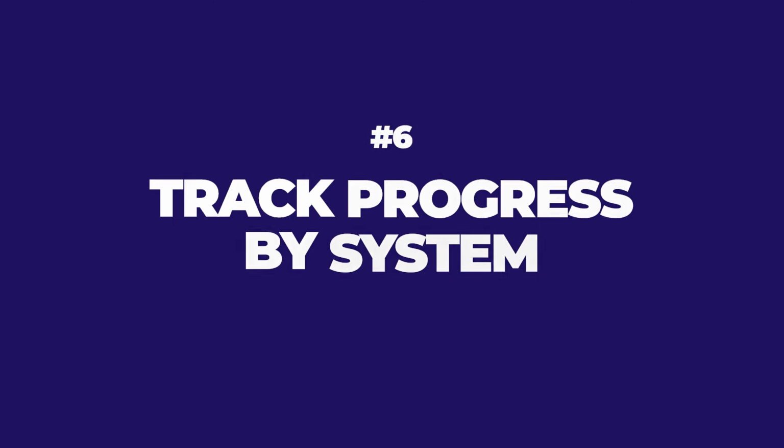Number six, like I said, track progress by the system, not by location. I wouldn't do it floor by floor. I literally would get out those flow diagrams and those one-line diagrams, and that's what I did on the first project where I was doing this, to schedule dates for different segments and pieces of equipment and how they tie together, and then highlight them as they're installed. And when you're ready to actually do the startup and the commissioning for the systems, you will be tracking it by system and connection and intersection, and you will not get lost in the geography of the building, and you'll really be able to orchestrate a nice sequence that will get you to the finish line faster.